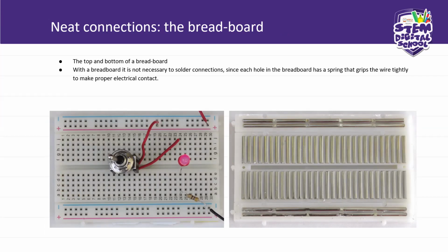Okay, now this is the top of a breadboard. A breadboard looks like this. A breadboard has its polarity already set up. As you can see, you have a negative line there, you have your positive line there, and then these holes, they all have polarity. So when you connect your components on a breadboard, check their polarity. Remember, I talked about polarity of components. Like the LED has a polarity, your diodes have polarity.